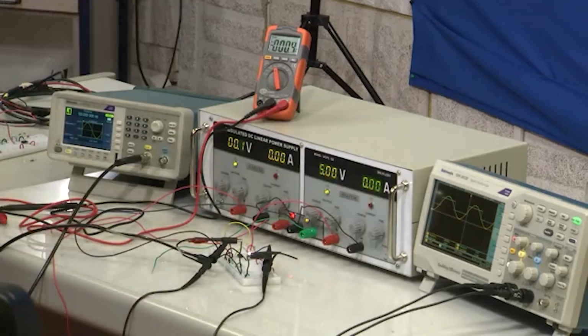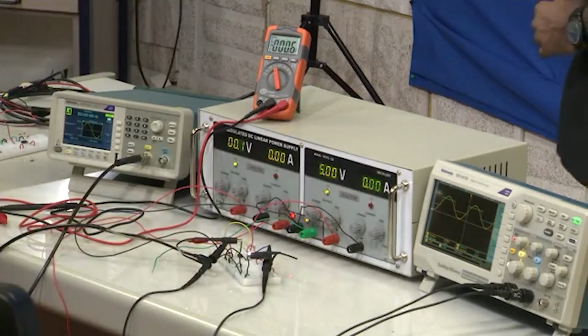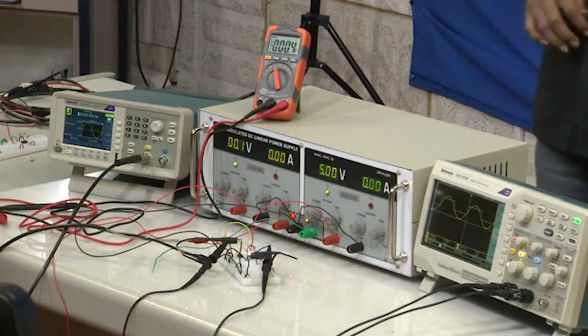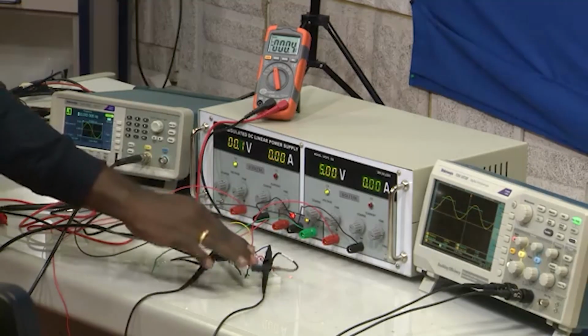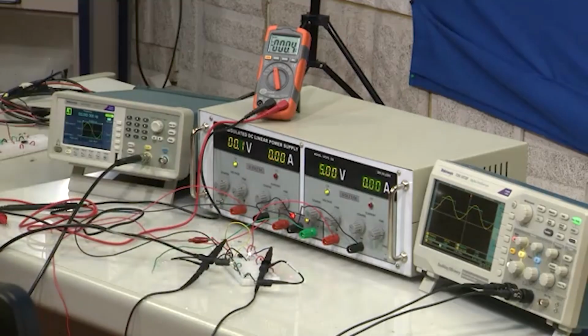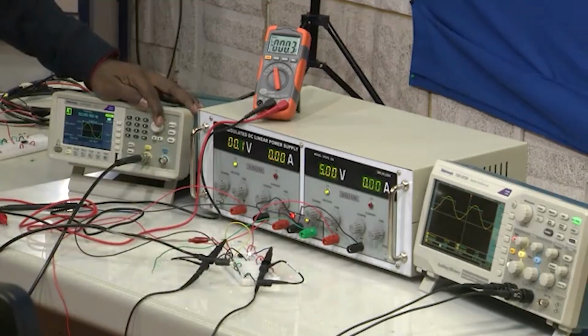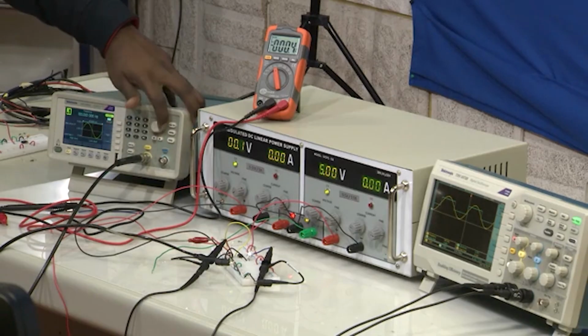That means that even though we apply a sine wave, the output is what? 0 and 1. Indirectly we can say the output is nothing but 0 and 1, that is a square wave, right. So, this is the beauty of the comparator, that your input signal is a sine wave, your output can be a square wave, alright.